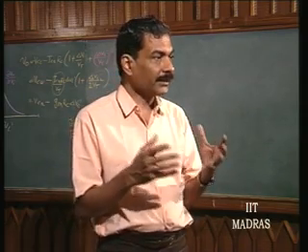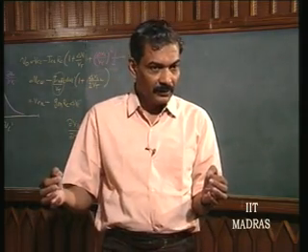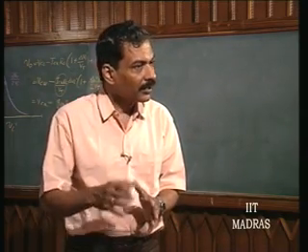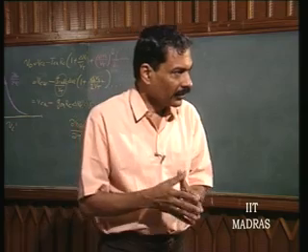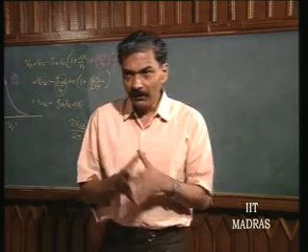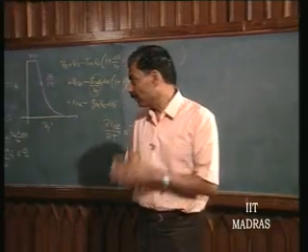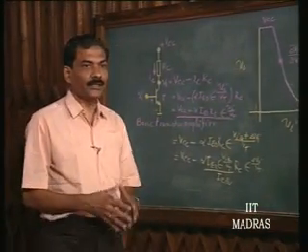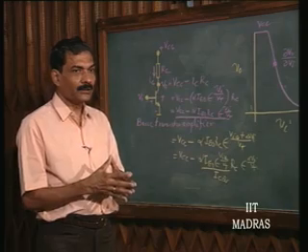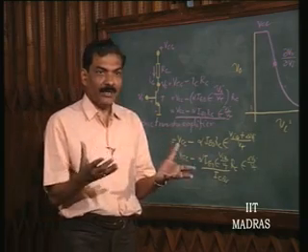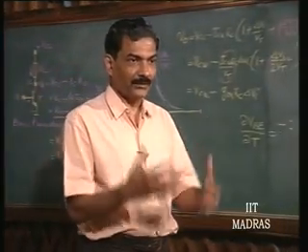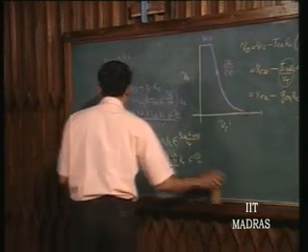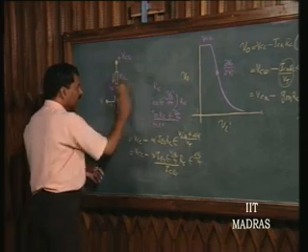For high frequency signals, at least I can decouple this, okay, and only extract the high frequency part and couple it on to another stage. So, it is not going to be a problem, but for low frequency signals this is going to be a problem. So, that is the reason this stage is not preferred in integrated circuits. In integrated circuits, we would like to exploit the property of the device to compensate for this. Straight away, I would say that one technique is to see to it that this is modified somehow.